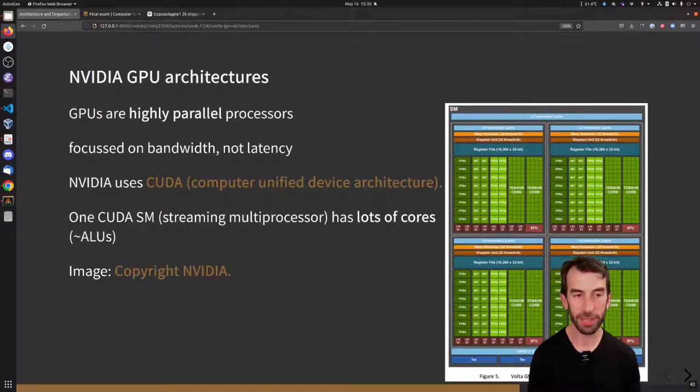So the idea of a GPU architecture is taking this SIMD idea to an extreme, right? On a CPU, there was the idea that you could get a graphics or signal processing pipeline sped up by having one ALU process a couple of different things at the same time. And then on a big graphics card, they want to speed up a pipeline of huge amounts of pixels having the same operations going simultaneously by just having heaps of ALUs.